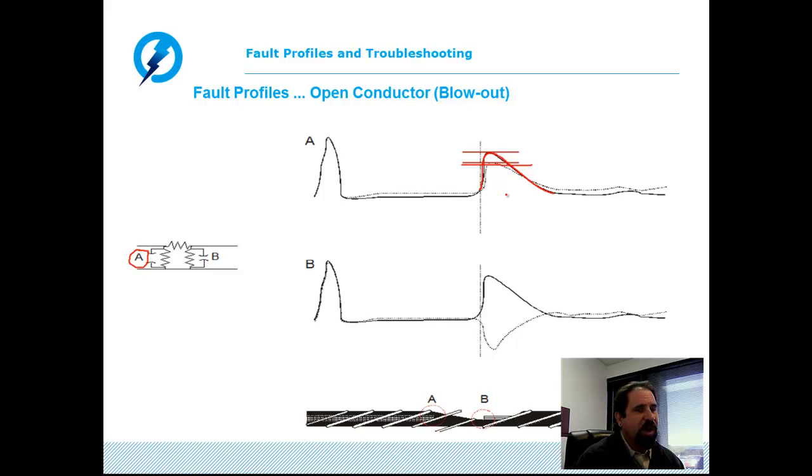The fact that when I ran the arc reflection test I got a very small or subtle change is also a clue to me saying thumping conditions may not be very good. I may not be getting very hard thumps, and in essence this may make it difficult for me when it comes time to do pinpointing, because I may not be getting the maximum amount of energy and in essence the maximum amount of sound from the fault. So pinpointing may be a little bit difficult.